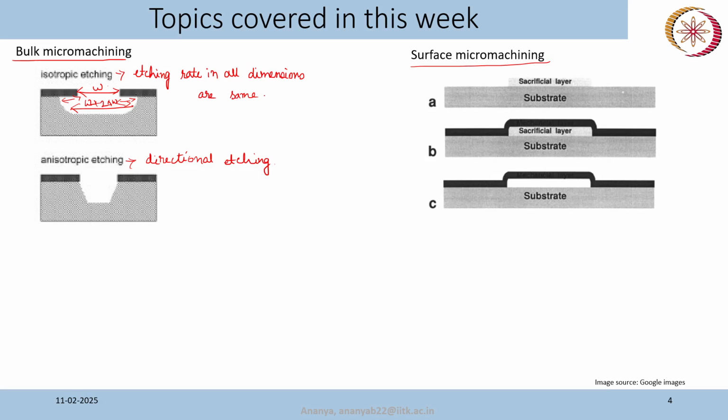So you will not be able to get a proper dimension as you actually wanted. In that case dry etching is preferable if you are working with critical dimensions, but you need a certain machine for that, and usually these are very slow. Okay. Now the best of these two will be reactive ion etching, or dry reactive ion etching, where you use both chemical etching and dry etching techniques, combining both to get anisotropic or directional etching with a much faster rate. Okay.